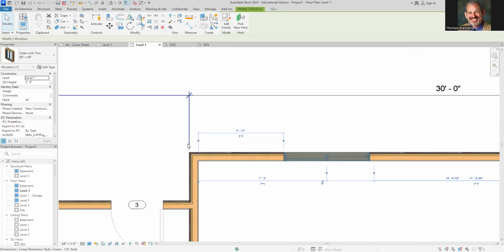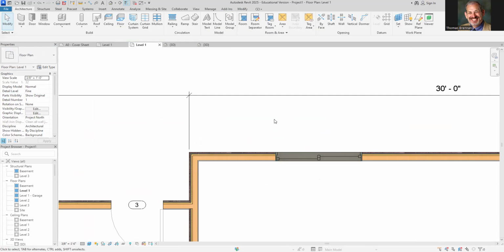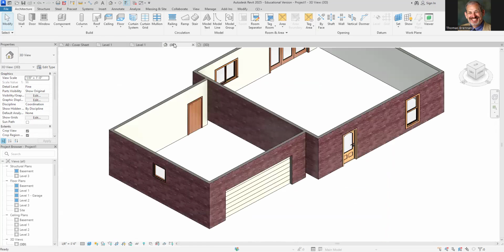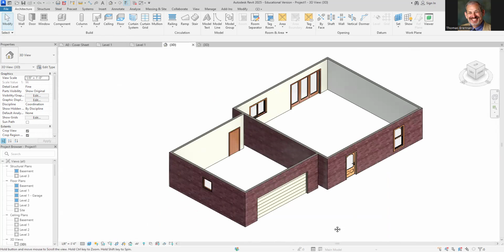Click on this, your temporary dimensions. We click on this, we move that there. We move this to the center and make sure it goes in the center. And that's got to be 17.6, just like that. All right, now at this point, we have it built. And then when you take a look at it in 3D, it's going to look like that. That's a really good start.